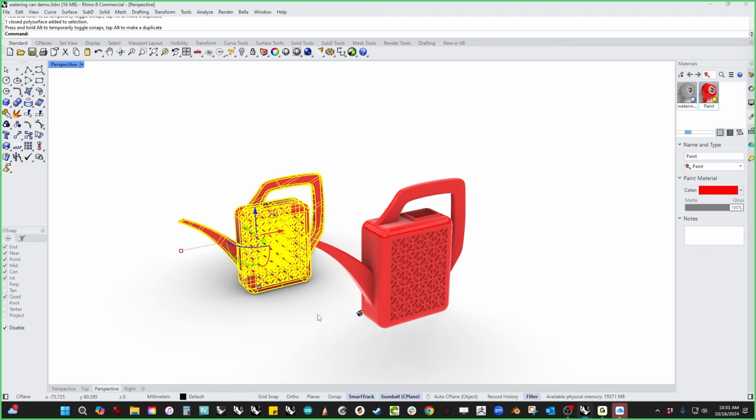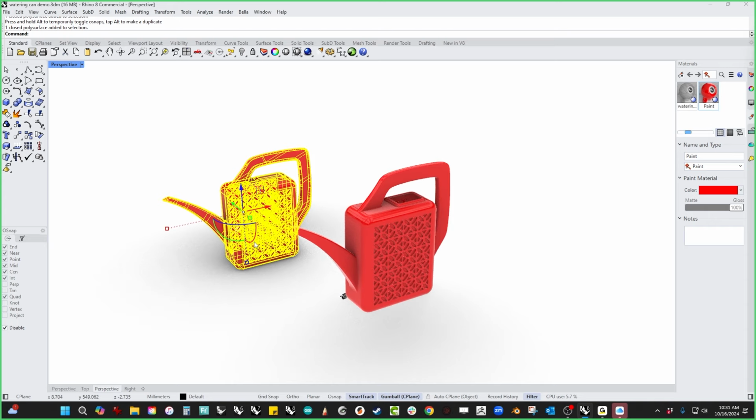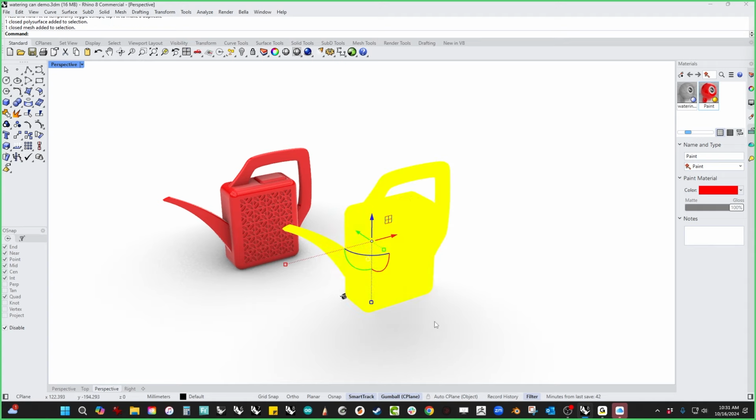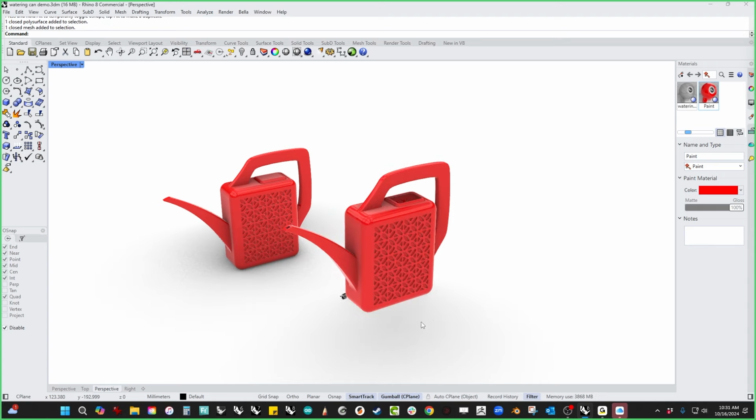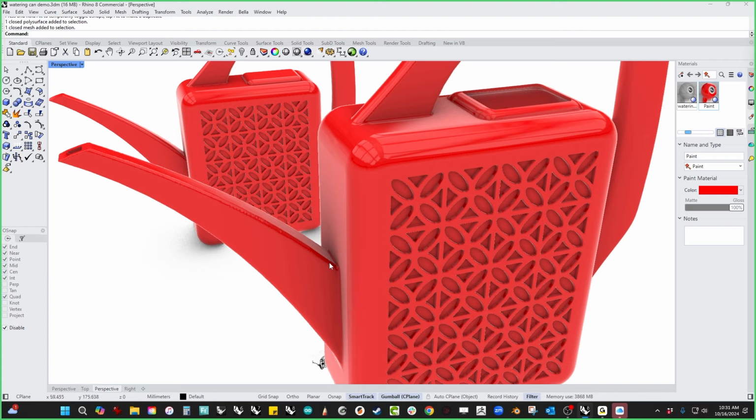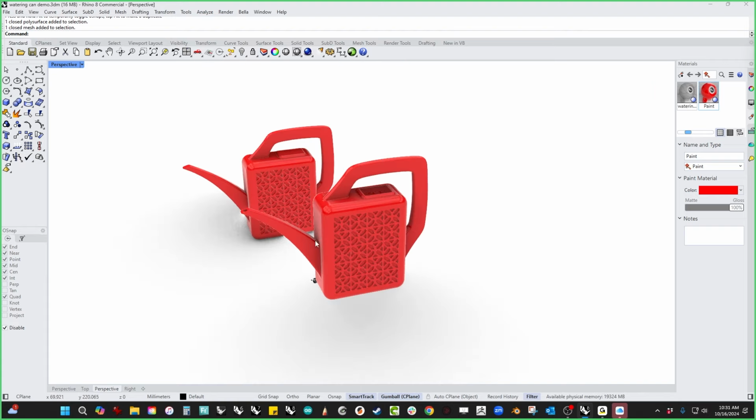All right, so that's how you can go from fully nice clean CAD. This will data transfer all day long. SolidWorks, UG, Pro E, all that kind of stuff. This goes to a printer shelled with wall thickness and all that stuff. So pay attention to areas inside like this. Just make sure that when you do the smoothing and stuff, you don't over smooth inside corners because you can make them thin.